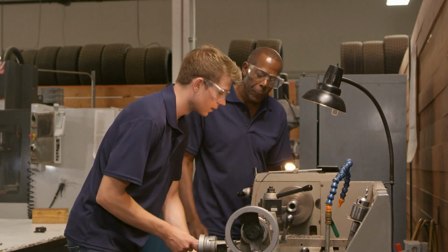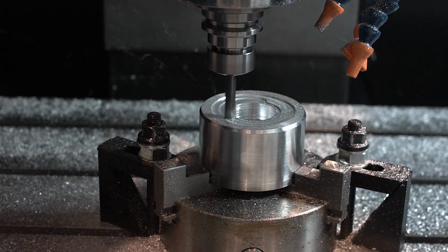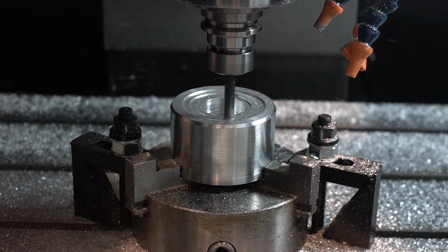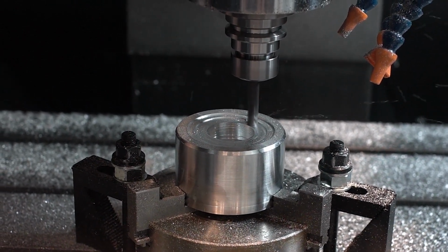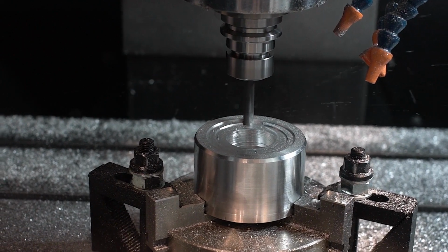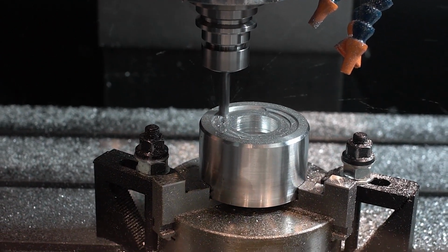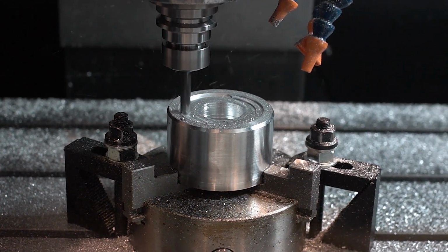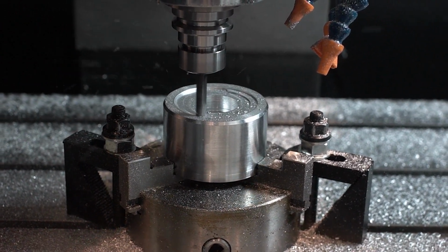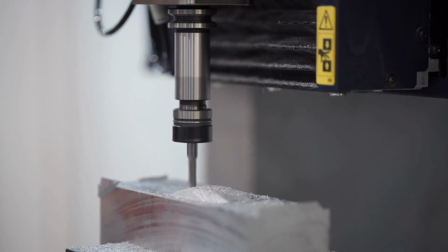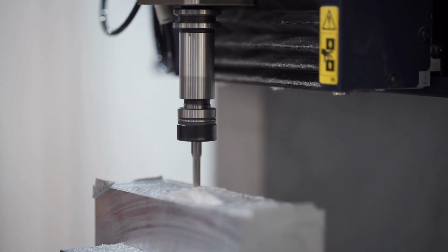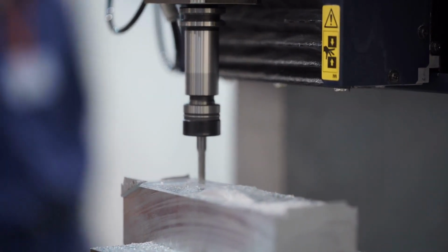To make writing CNC programs easier, we use a different coordinate system designed for human manipulation called a Work Coordinate System, or WCS. The WCS defines a particular origin point on a block of material, usually in CAM software like Fusion 360. You can define any point on a block of material as the origin point for a WCS. Once an origin point is established, you will need to locate it inside your CNC machine using an edge finder, dial indicator, probe, or other locating method.